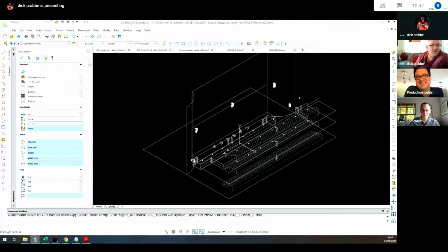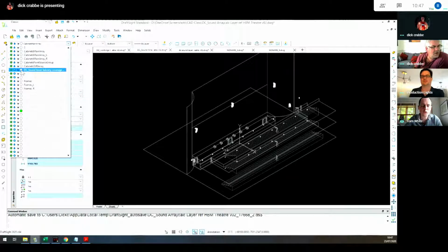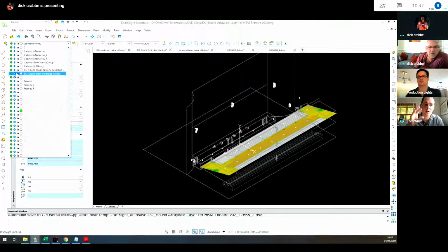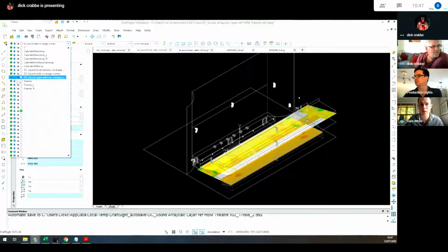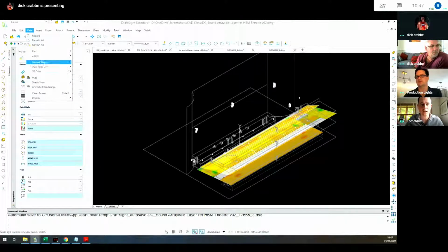And I am still sharing, aren't I? I'm just going back and one last thing. I think we talked about the benefits of producing an A4 or A3 or A1 layout is that you can replicate the drawing in an identical manner every time. In comparison, you print from model space, which, there's no problem whatsoever printing in model space, but it's quite challenging to repeat the process.